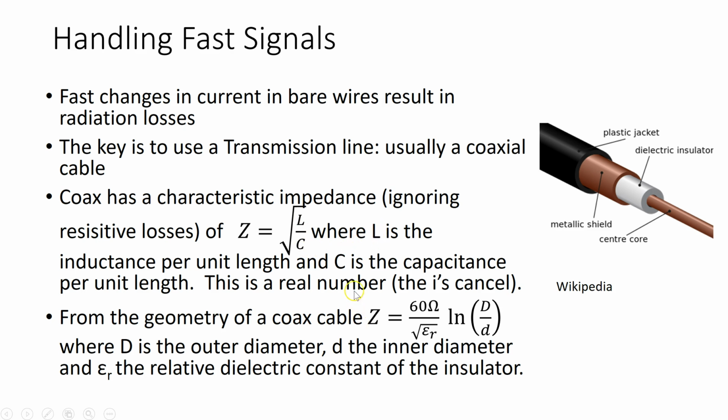You'll remember from the formulae for capacitive and inductive reactance that they each have an i in them, the minus i in one case and a plus i in the other. So this has a minus times an i times an i, which then is just 1. So this is real, and the value of the impedance of the cable then is real and just usually 50 ohms, and I'll explain why in a minute.